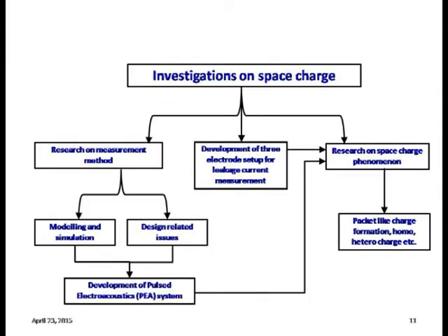So these are the basic investigations we have planned in our research lab: research on measurement methods, and after identifying a measurement method, modeling and simulation, and design and development of the method. That's what we have used, the pulsed electroacoustic method for measurement of space charges. After that, we developed a 3-terminal electrode setup for leakage current measurement also.